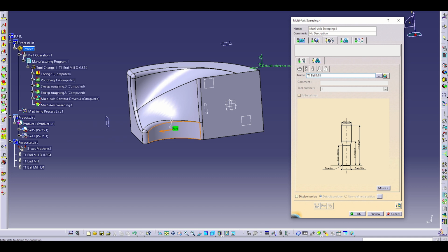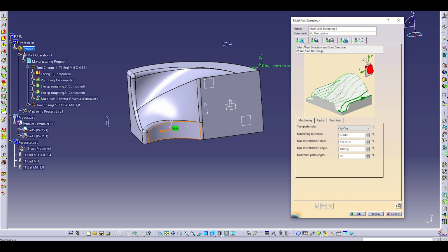Especially in the last one I didn't have to use a ball end tool, but since we're kind of going in a divot, we're going to have to use a ball end bit to make sure we are not gouging the part and make sure the curvature is nice and smooth. If you're cutting around like the backside was, you can use that end mill, and the 5-axis will actually guide it exactly how it needs to be to keep it flat. But since we're going inwards, it would gouge the part, so we need that ball end.